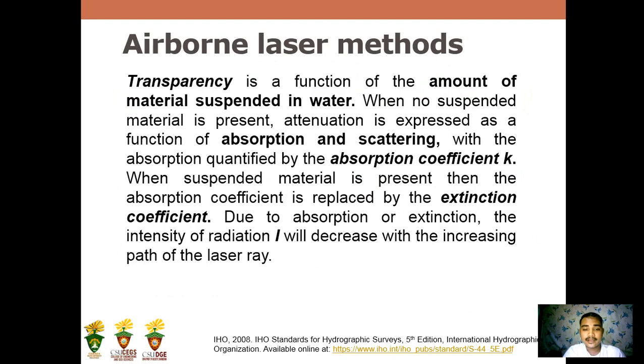And transparency is a function of the amount of material suspended in the water. Especially in hydrographic survey, the transparency of the water affects it. Especially when you survey a brown river, the elevation of the bottom cannot be compared because of the suspended sediments.